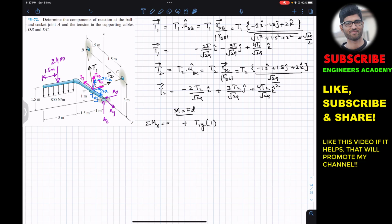And similarly, T2y is going to produce a moment about the x-axis in this direction. If we curl our right hand fingers in this direction, the thumb will point out in the negative x. So this means that T2y is producing a clockwise moment about the x-axis. So I will write minus T2y, and again the moment arm of T2y from the x-axis is 1 meter, so we will multiply this with 1. This is equal to 0, and from this we can say that T1y is equal to T2y.